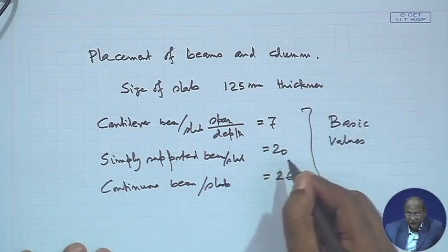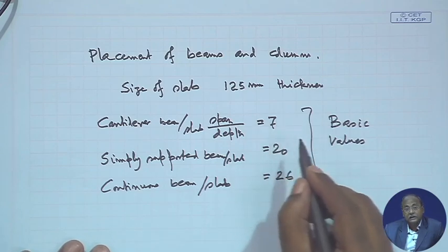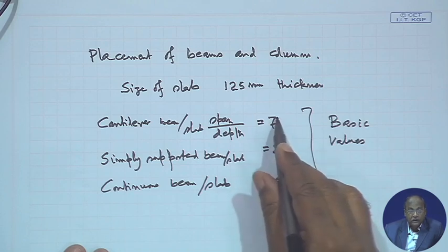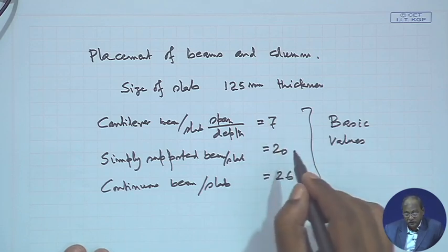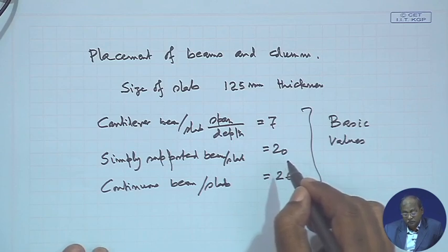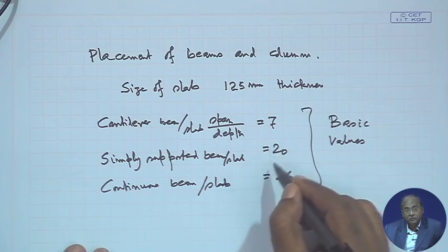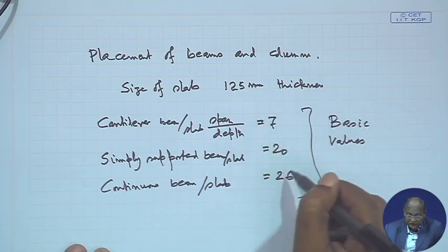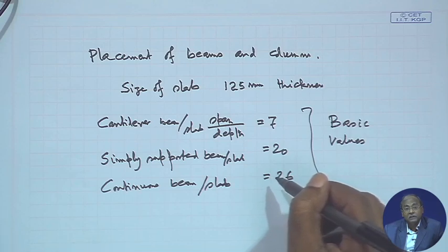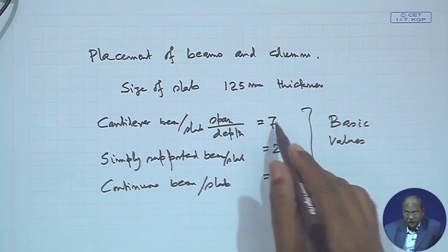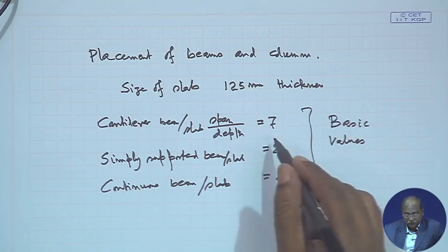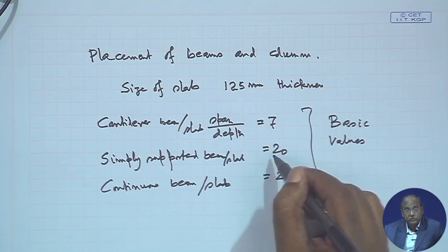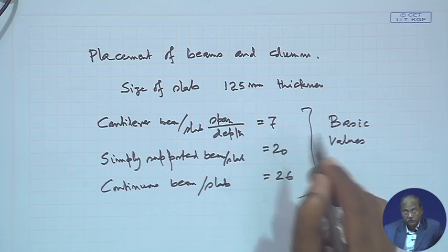And these are modified with different kinds of steel and other aspects, which you can find in IS 456. This is a very, very important aspect in design. Before you start, we shall come back to analysis, then we shall discuss that. Whenever we discuss this, it will give you the basic, initial dimension, and that is very important here, the span by depth ratio. Sometimes we get a span by depth ratio that may be less also, and on the basis of that we can decide.